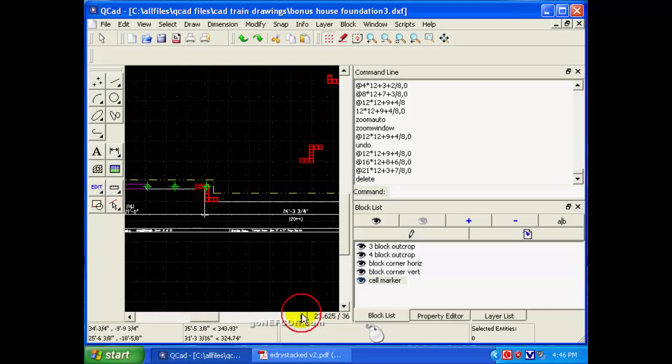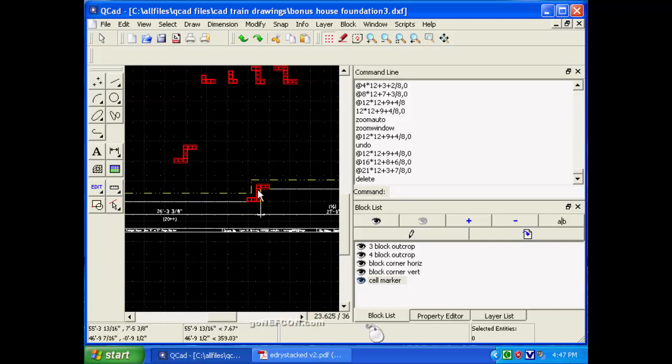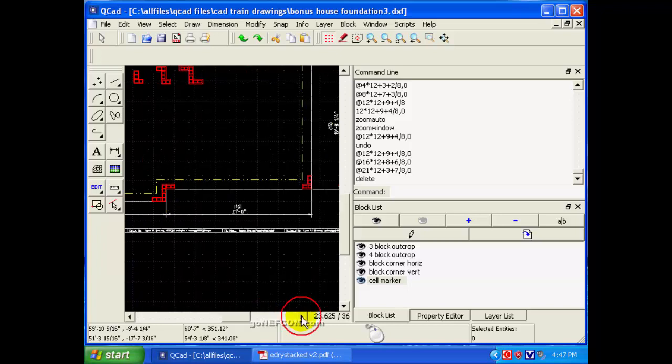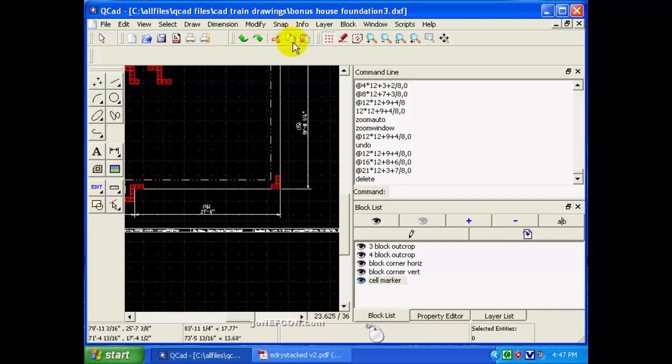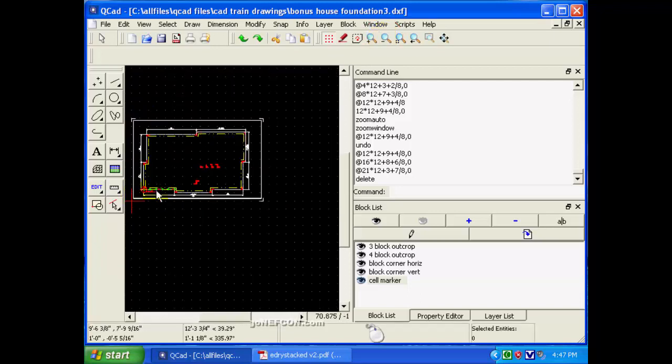As you continue on, you would simply continue on from that same reference point to set these items here, any windows, doorways, whatever, until you get to this corner. Notice there has to be one in this corner and this corner both. Every corner requires a cell, rebar cell. So all the way across the face of that page, then you can start from this corner and go up, measure in that direction. So you want to measure all your cells along one wall segment from one given point. That way, if there's any a little bit of air, you won't keep adding air to more air and more air. It all starts from this point.